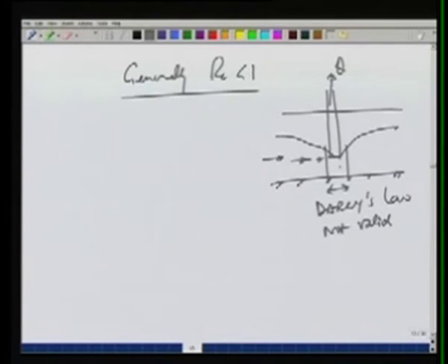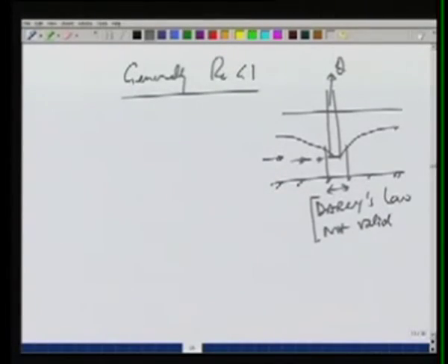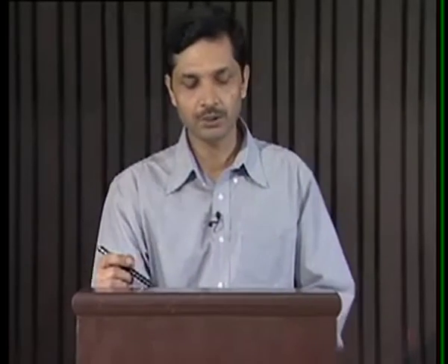If the velocity is very high, so for high pumping rates very close to the well, Darcy's law may not be applicable. Similarly, for flow through gravels, sometimes we may get velocities which are very high and Darcy's law may not be valid. So when we apply Darcy's law in order to derive the continuity equation, we should be aware of the limitation that the Reynolds number should be less than 1. So we have to check the Reynolds number and ensure that it is less than 1, and then apply Darcy's law. The second thing which we notice in Darcy's law is this term K, hydraulic conductivity.